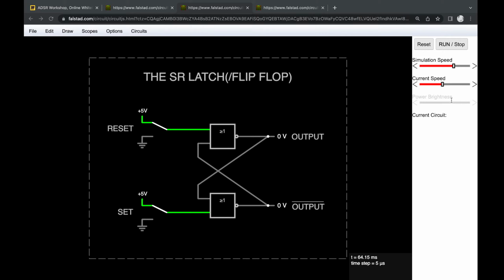Bastionix asks, if I may ask, is it cool to use a regular gray diode instead of a signal diode for the VCO core? Well, the problem here with the diode is you want a diode that reacts fast. And for that, traditionally, the signal diodes are best.